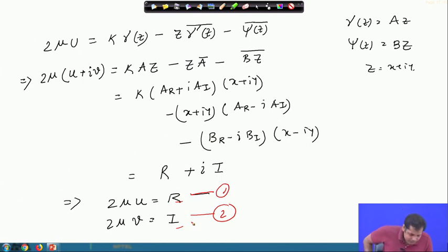Okay. So, you see, the objective of this exercise has not been to really solve any boundary value problem. The objective of the exercise that we have just done here is to try to convince you why this particular form, sigma xx plus sigma yy and sigma yy minus sigma xx plus 2i sigma xy, that particular form is used. This is how this particular form can be used and can ease our problem in solving this equation.